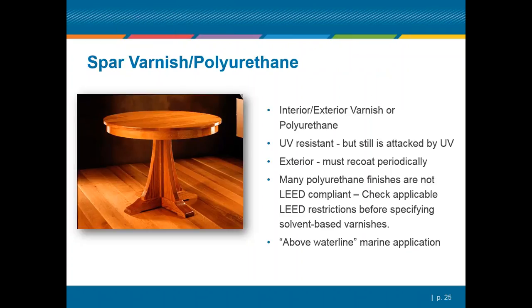Okay, now, wood finishes that can be used exteriorly. Spar varnish or polyurethanes can be used exteriorly. Some of these polyurethanes are interior-exterior in nature, and spar varnishes are very moisture-resistant varnishes that can actually be used above the waterline in marine applications.